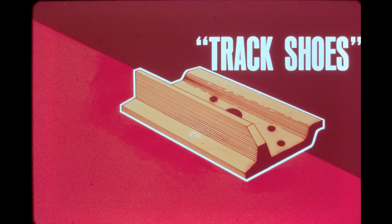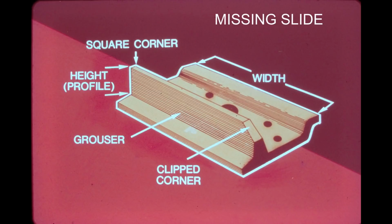In order to meet these requirements, track shoes are available in a wide range of sizes and widths, with varying profiles and metallurgy. There are various aspects of dozer track shoes relating to specific applications. For example, a machine can be equipped with severe service shoes in lieu of the standard shoes. The severe service shoe has a thicker grouser than the standard shoe. Standard shoes are used for general contracting, topsoil movement, and for agricultural work. Severe service shoes are normally used where rock is prevalent, such as in mines or quarries.